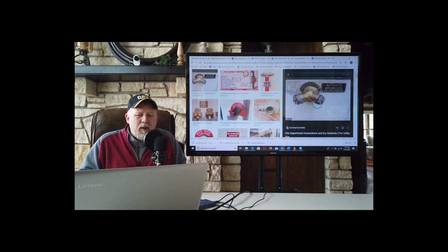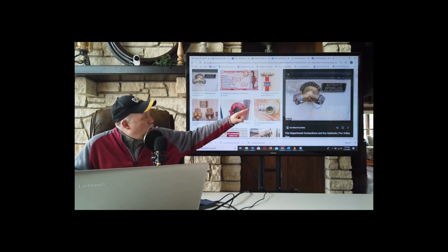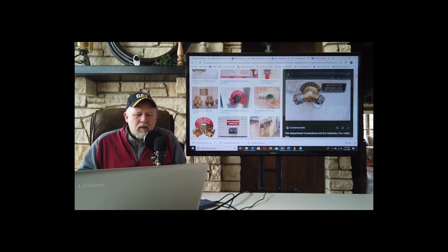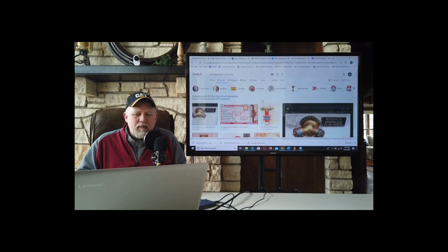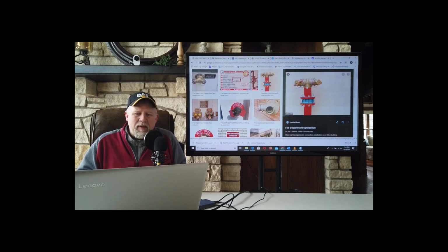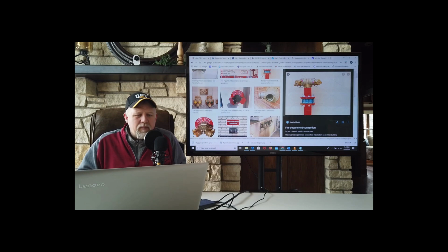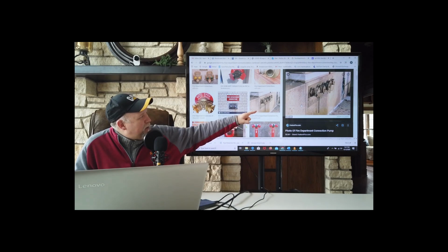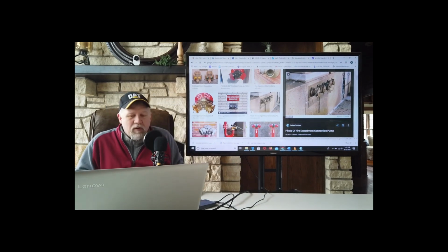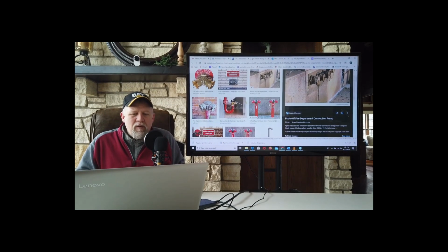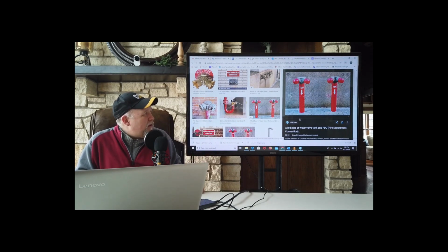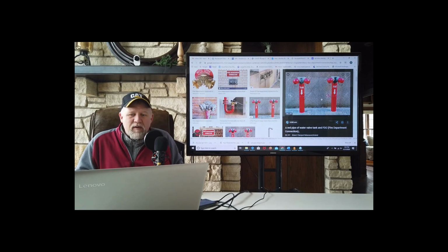And they're going to use their pumper truck to boost the pressure within the automatic sprinkler system or the standpipe system, whichever it is. In other words, and here, this is one type. Let's take a look at what you might see. You might see a connection like this on the outside of a building, like a brass plate with several fire department connections there. You might see a pipe sticking out of the ground like this, fairly close by, where it says FDC, fire department connection.